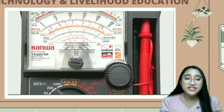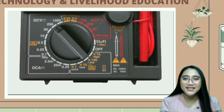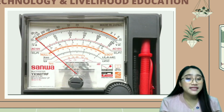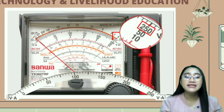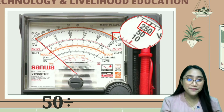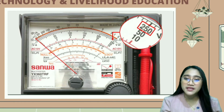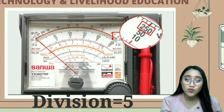Now let's change our range. Let's put it at 250 direct current voltage. Let's go back to our scale. The scale that we are going to read is from the 250. Now let us know the values of each division at the range of 250. There are 10 divisions at 50. 50 divided by 10 is equal to 5. Meaning, every division at 250 is equivalent to 5.